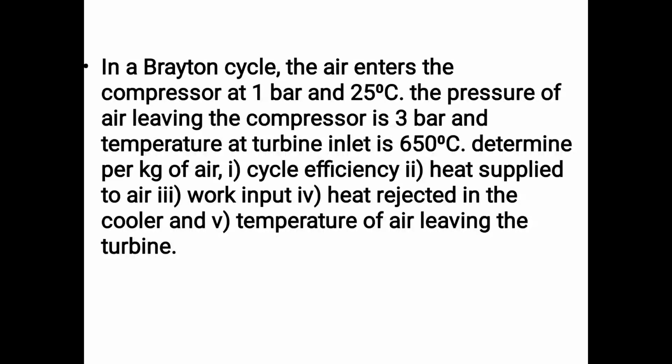Next, we are going to see the Brayton cycle problem. In a Brayton cycle, the air enters the compressor at 1 bar and 25 degrees. The pressure of the air leaving the compressor is 3 bar and temperature at turbine inlet is 650 degrees centigrade. Determine, per kg of air: first, cycle efficiency; second, heat supply to the air; third, work input; fourth, heat rejection in the cooler; and temperature of air leaving the turbine. First, you should draw the schematic diagram of the Brayton cycle. Then only you can take the data correctly.